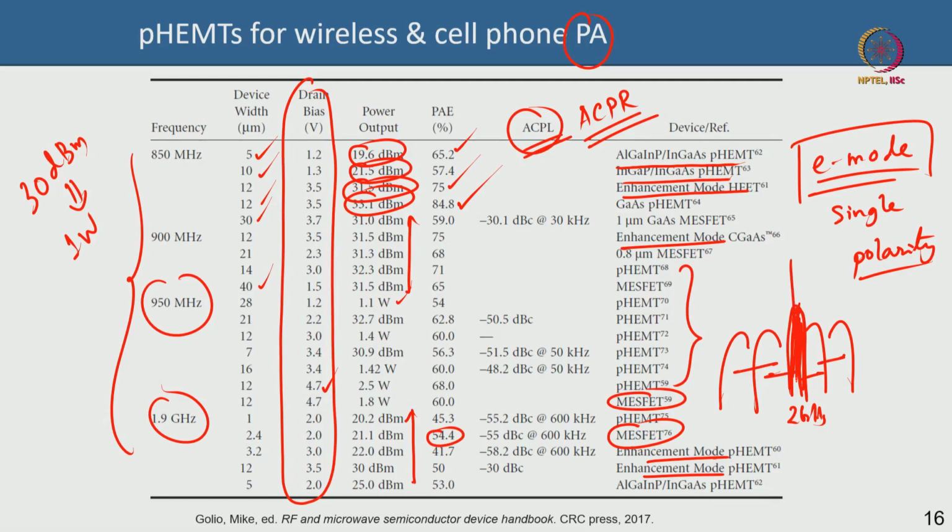Compared to this center frequency, that is why this C comes, dBc, with respect to the center frequency, how much power are you leaking into the adjacent channels, the first adjacent channel, that is your ACPR. It should be as low as possible. So how much power you are getting in the primary channel as opposed to how much you are leaking into the adjacent channels, that is your adjacent channel power ratio or adjacent channel leakage ratio, power leakage, etc. Different companies use different terms, but in a sense this is the main idea.